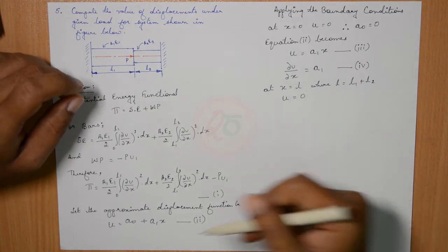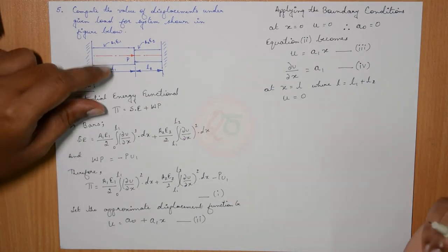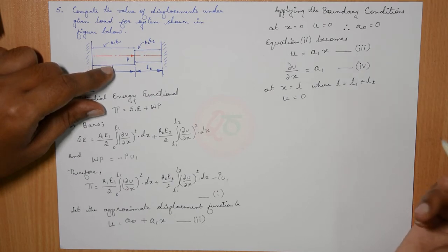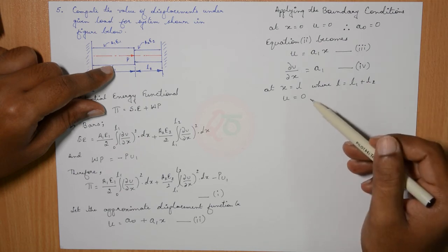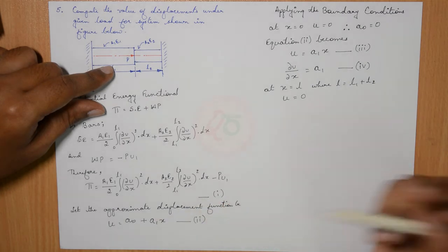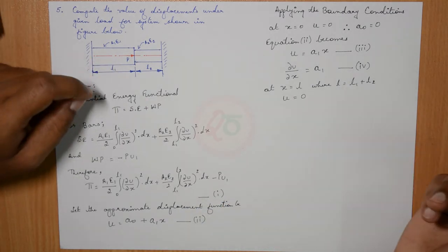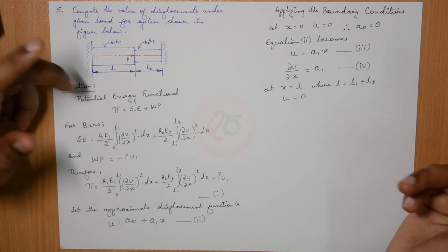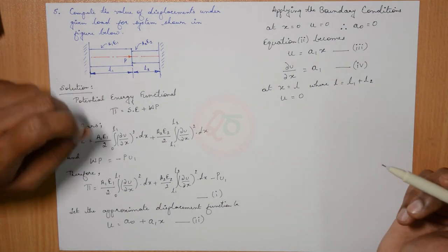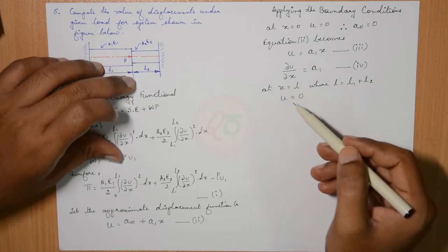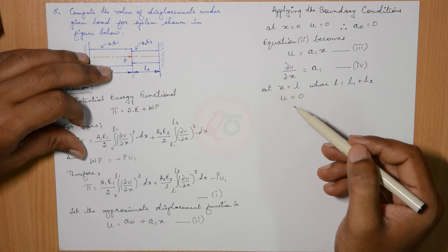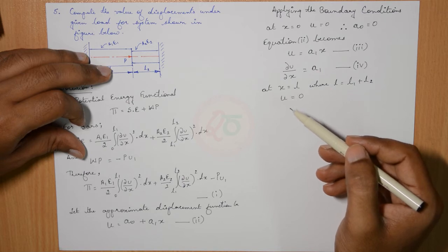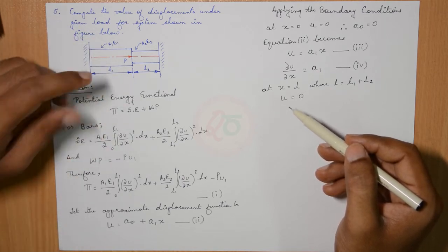Now if you look at the equation that we have assumed, it is a single degree polynomial. It is not the second degree polynomial. For a single degree polynomial, if you substitute this boundary condition, this becomes a1 into L, and for that a1 into L, a1 becomes 0. So the very purpose why I took this boundary condition is in order to let you know that whenever you are dealing with first order polynomial approximations, don't try to apply the boundary conditions in an overly manner.